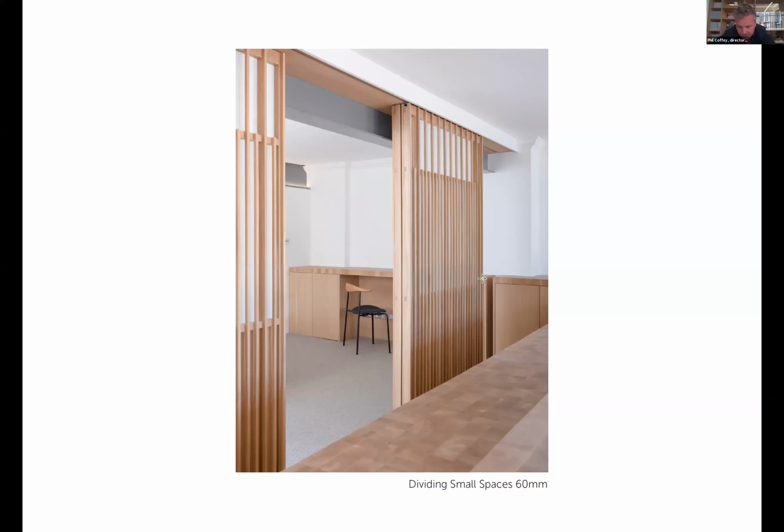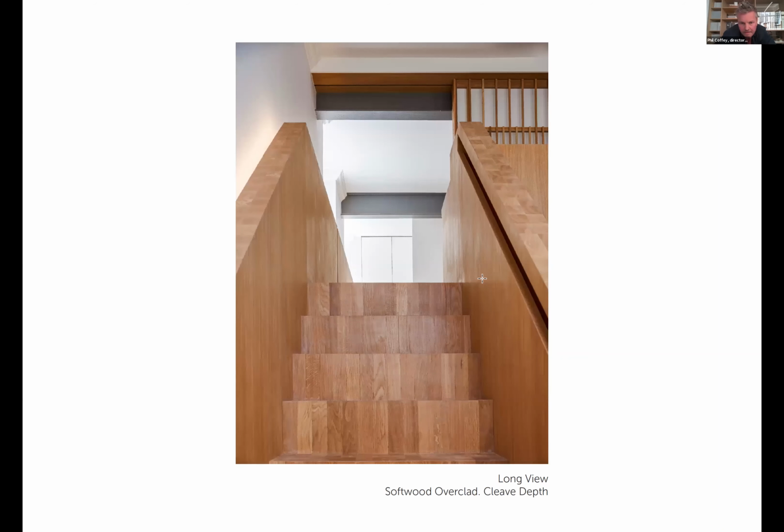This is upstairs. Somebody once told me that once you've sketched out a layout, you should always put a grid on a plan. A 60 by 60 grid is a particularly fine grid to put on a plan. But the wonderful thing about putting a grid on is then you actually start to detail to 60 mil and draw to 60 mil for layout. And then you find little nooks and crannies, pockets, desks, where screens should sit. So the material itself helps you in the wider context of laying out the initial outline plans, which I find an enjoyable relationship between material and function and layout.